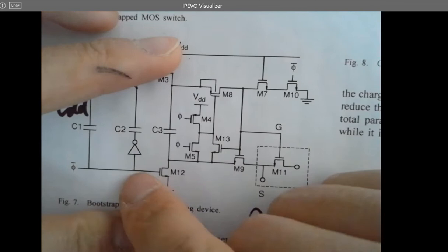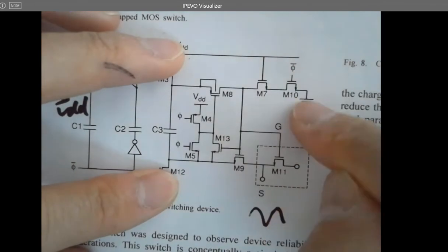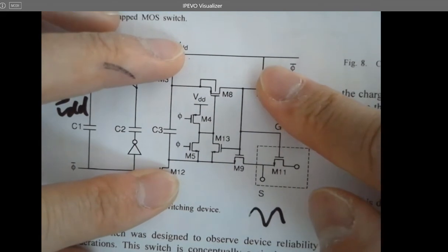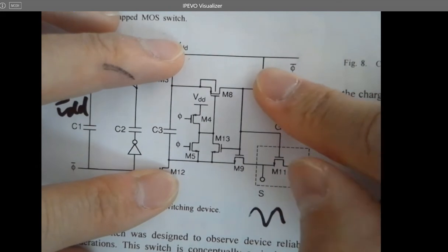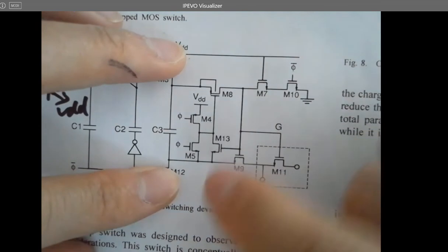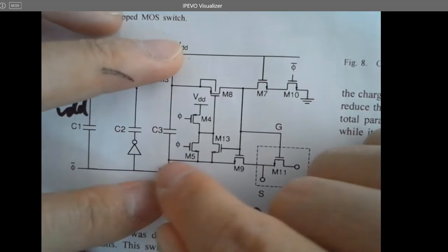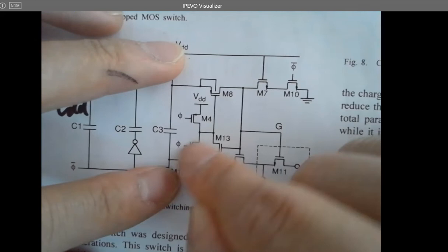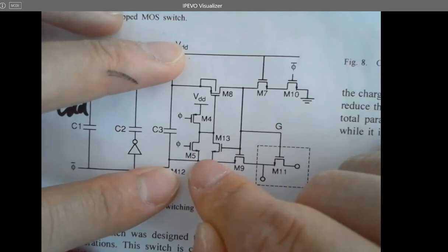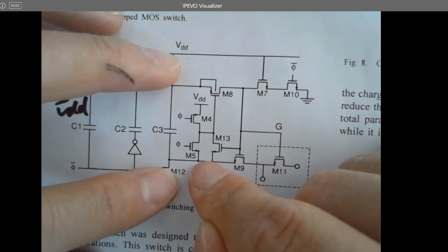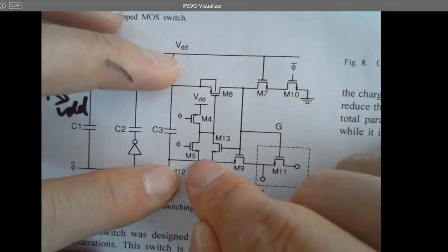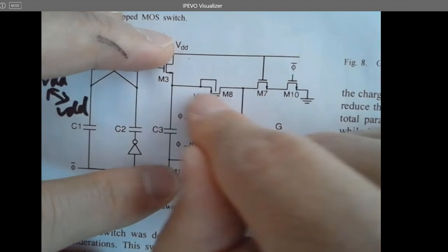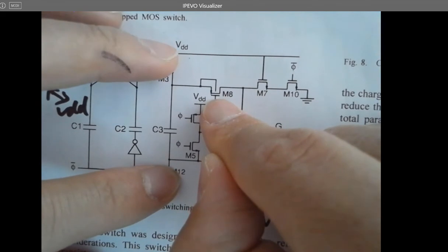So now, as we know, this is low and this is low, so it's cut the connection from here to the ground. So it's not affecting the circuit anymore. It's not resetting the circuit anymore. Okay. So this is gone. And because this is low, so phi bar is low, so phi is high. So whenever phi is high for this inverter, it's pulling this point to this point, which is a lower voltage. All right. Whenever this is a lower voltage being applied to the gate of the PMOS, and this is still VDD, so VDD minus VG of the PMOS is larger than VTHP, so this is on.